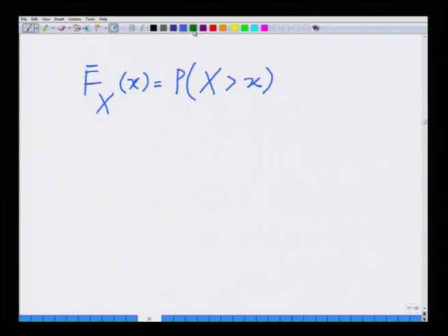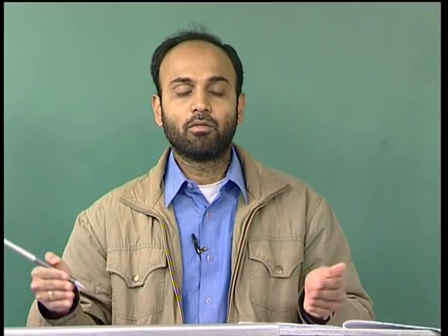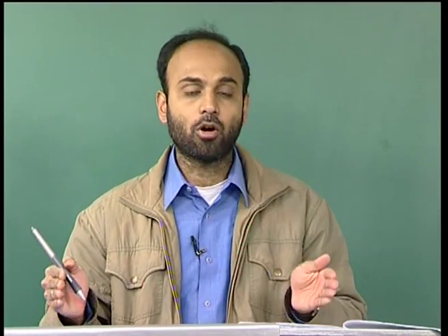That is, this x can be this random variable, which is essentially the PAPR. Remember, because the symbols are random, the instantaneous power or the peak power for a group of symbols is random depending on the combination of symbols. Hence, it is a random variable, and it is best characterized by a distribution function. Here we are using the complementary cumulative distribution function.